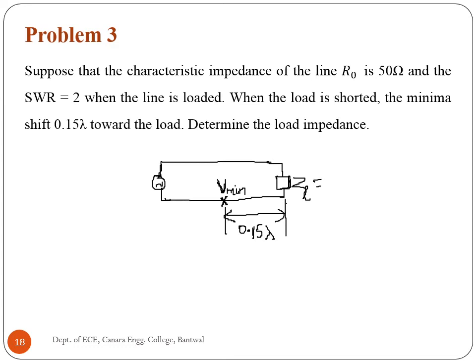Then I have to find out the load impedance. From the first V minimum position, if I travel towards the load, I'll get the ZL value.